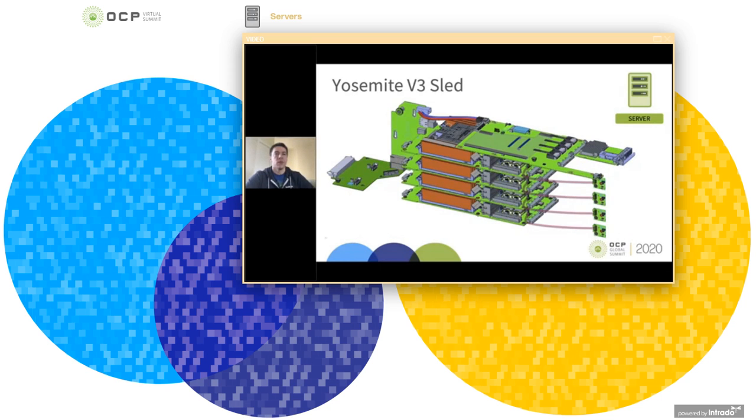And I also wanted to show just what one complete compute-focused sled would look like here, where you can see we have 4 Delta Lake motherboards all connected in the same sled with the I/O cards of each sled server blade, and then to the baseboard that does the system management, and then the power architecture behind it. And this would be enclosed in a metal enclosure, fan modules in the back as well.